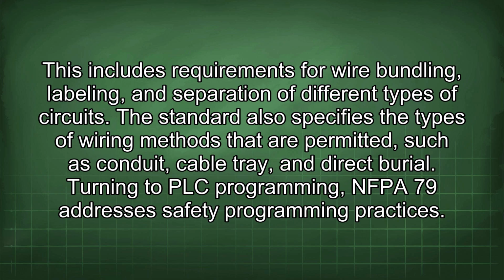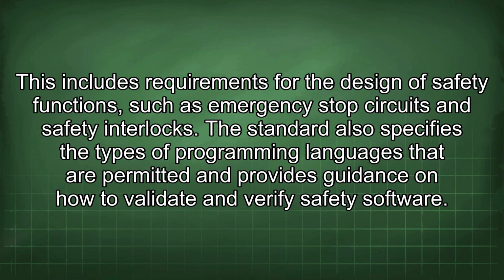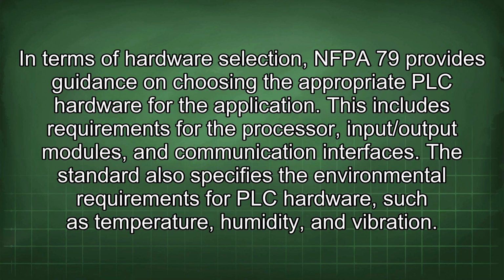Turning to PLC programming, NFPA 79 addresses safety programming practices. This includes requirements for the design of safety functions, such as emergency stop circuits and safety interlocks. The standard also specifies the types of programming languages that are permitted and provides guidance on how to validate and verify safety software.